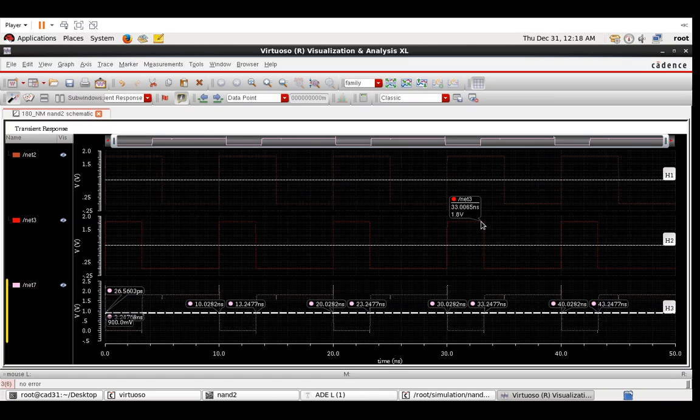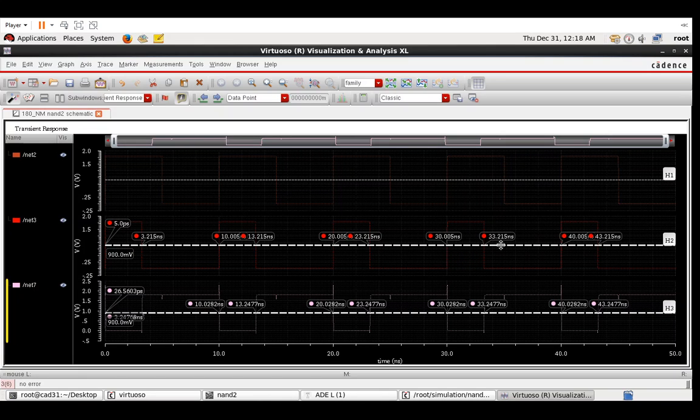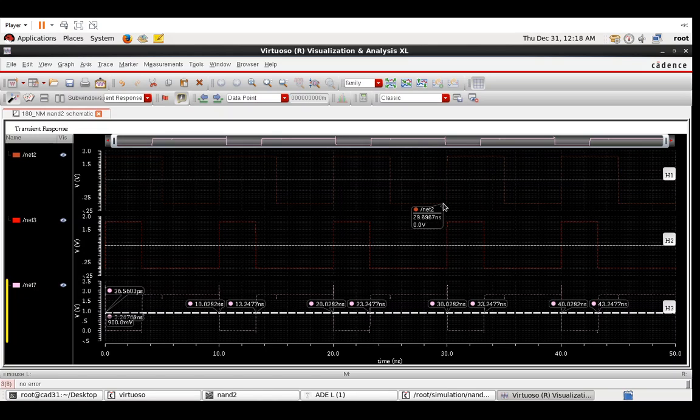Now there are two waveforms. This is the input waveform, this is the other input waveform. So you might ask, where is the 50% number to take? This is happening much before. This transition is not causing the output to rise. We want to find out which particular transition is causing the output to rise here. So this is one transition that might have caused it, this is another transition that might have caused it, and the right answer is this one.